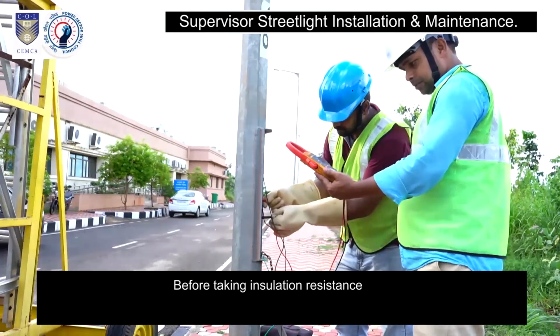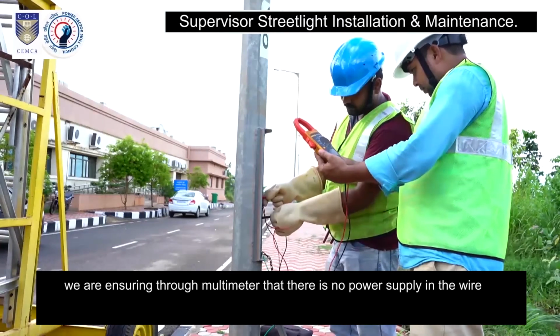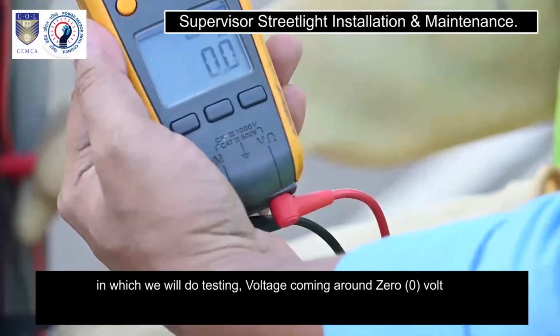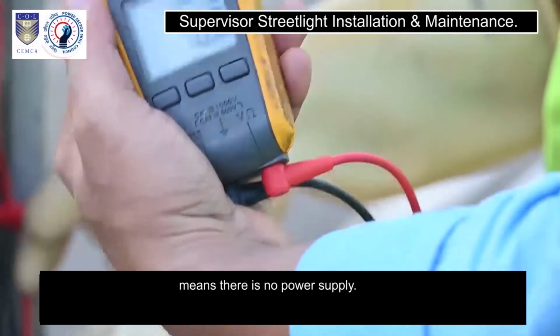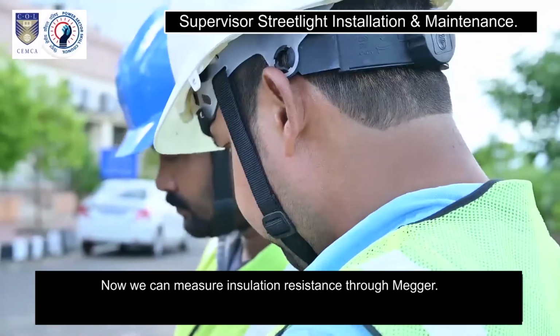Before taking insulation resistance, we ensure through a multimeter that there is no power supply in the wire in which we will do testing. Voltage around 0 volt means there is no power supply. Now we can measure insulation resistance through a megger.